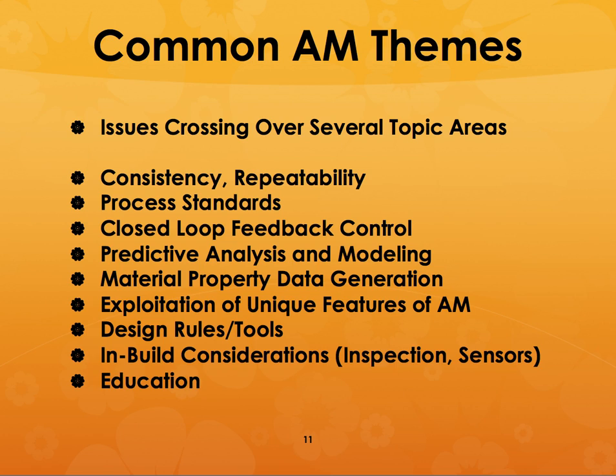The idea is that if you want consistency, say for example, if you can say that these are my properties with 95% confidence level, plus or minus 1 sigma or 2 sigma or 3 sigma and so on. It needs to be repeatable and it needs to be consistent. And with additive manufacturing, it was never that case. Nobody really cared about those kinds of issues in the past. But now we are, because we are making parts for actual applications. So we are making functional parts rather than functional form and fit.